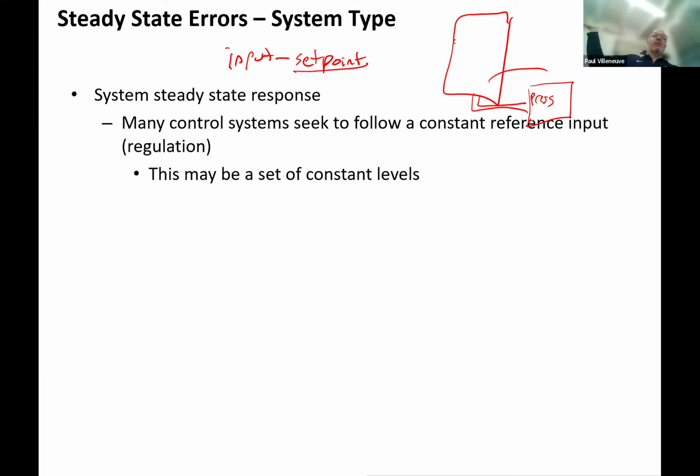If you're at the top of a mountain, the atmospheric pressure might be pretty low. So the pressure changes based on a bunch of different factors. To make this pressure measurement accurate, you need another port that just measures what atmospheric is. The difference between this input and this input is actually the water weight, or whatever the process is.